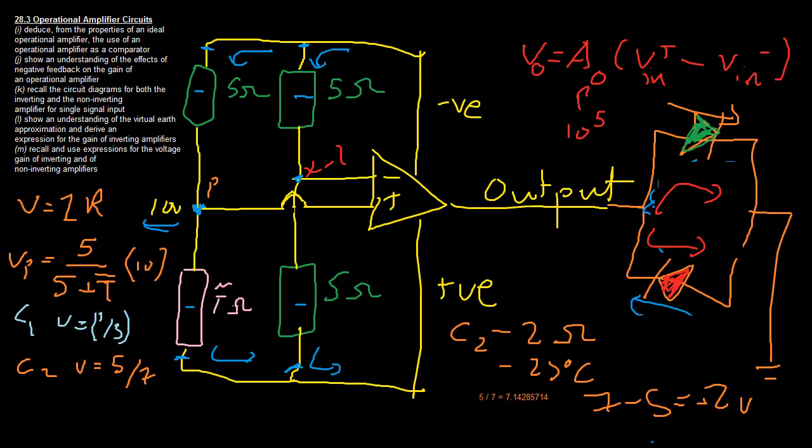But when the temperature rises enough and the resistance of this changes to be low enough, the voltage of this will overcome the voltage of the inverting input. So the voltage of the non-inverting input will become greater than the voltage of the inverting input in absolute terms, and therefore the whole direction of the current will swap round, and a different light will turn on. The green light will turn on and say, look, your sandwich or your food or your room is at the temperature you set. And what's more interesting is often, that temperature is not always the same.